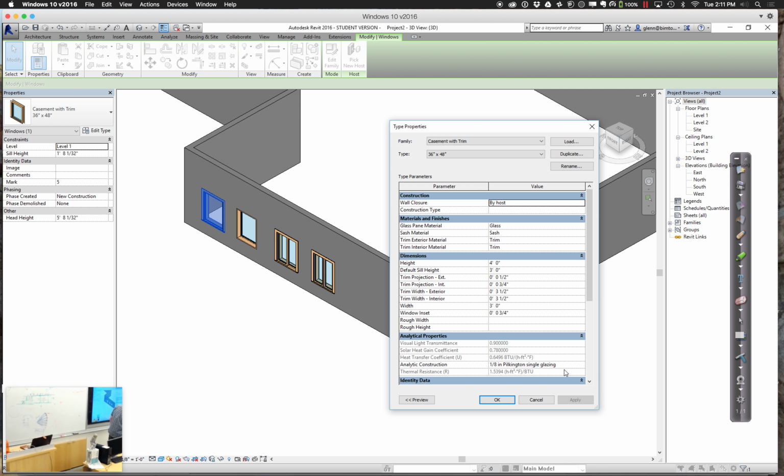Okay, so what does that mean? If this wall over here has an R value of, say, 45, and this is 1.5, that means the wall is 30 times as resistive as the windows. Or, real roughly, you can think about, inch for inch, 30 times as much energy passing through that window as passing through the wall.